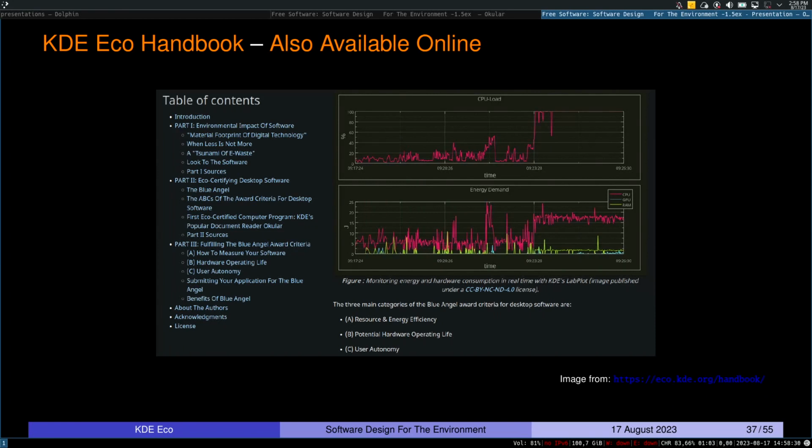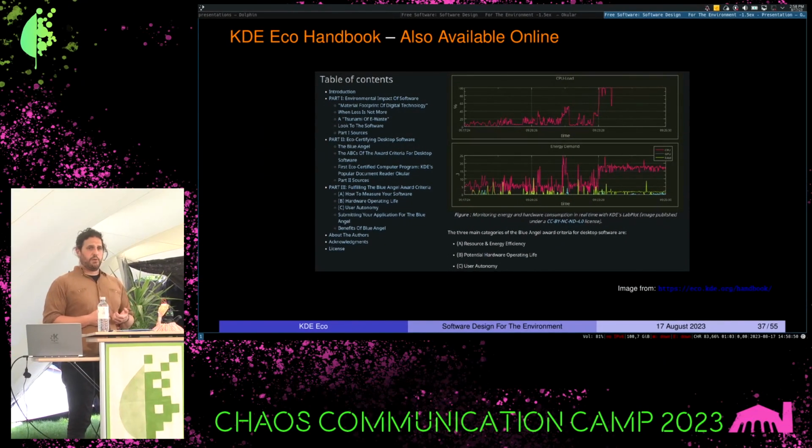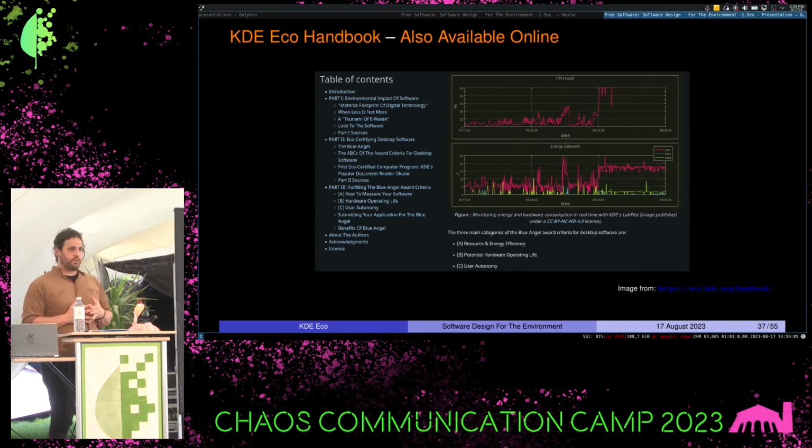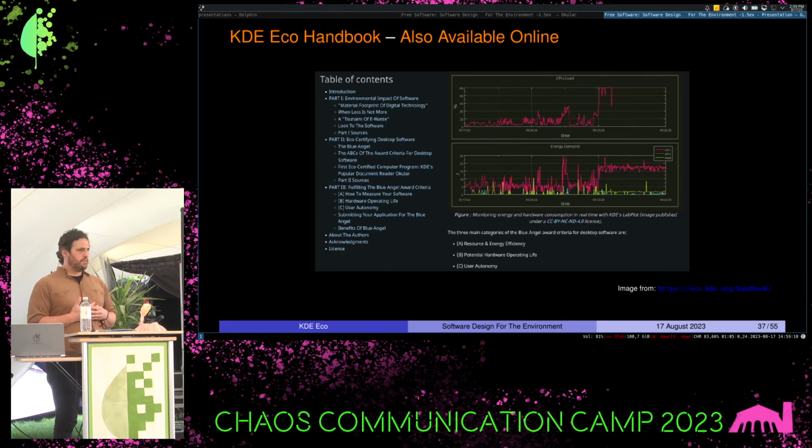For those of you who are interested in this but don't have access to a power meter. The approach that the Blue Angel recommends, and the one that we're using in our lab, is an external power meter attached to a machine that is then emulating user behavior. Power meters are expensive. Really good power meters are really expensive. The off-the-shelf solutions, which are okay, don't have great resolution. The one that is recommended, the Gude power meter, gets like 5 measurements per second, which you can then average and get an idea of what's happening.